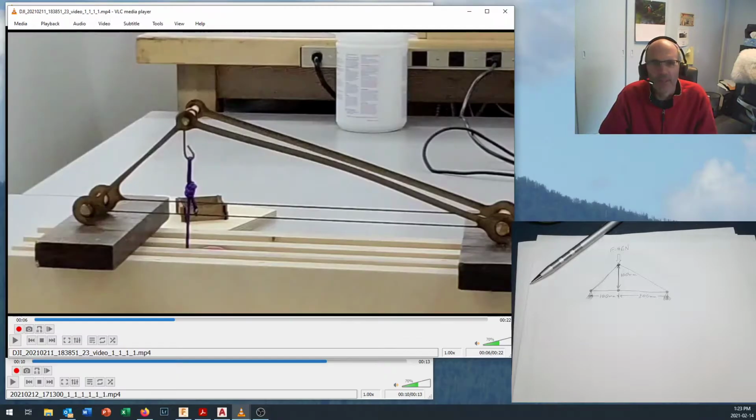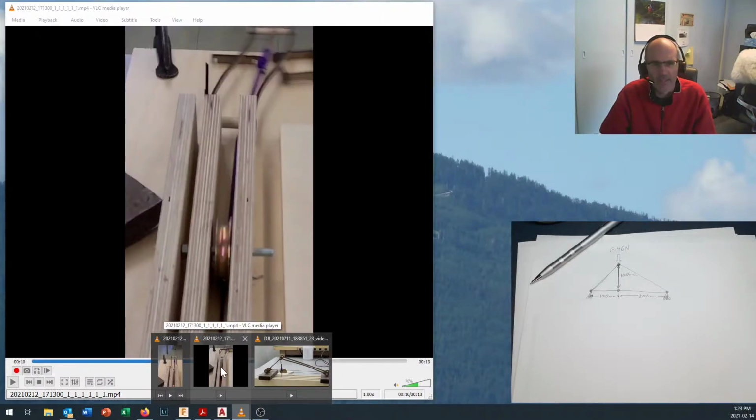But when we look at this structure right here, it doesn't look like that's free to rotate right around there. It looks like this is straight, restrained by this node, because this node is glued onto this piece of dowel that comes over here. And then it comes in, it goes straight for a little bit, and then it buckles out right here. And then it's restrained down at this end because this piece right in here hasn't flexed in or out either. So we've got slightly different loading conditions at the ends than we did on some of our tests. Now, this is something that I wanted to go and confirm.